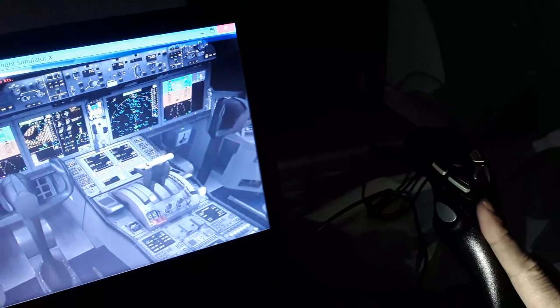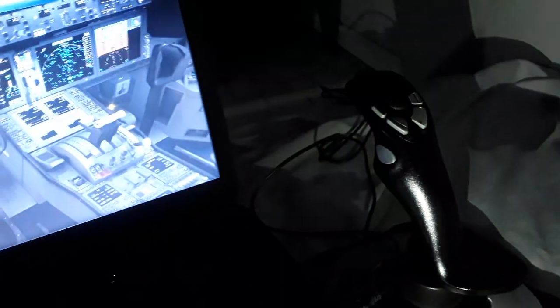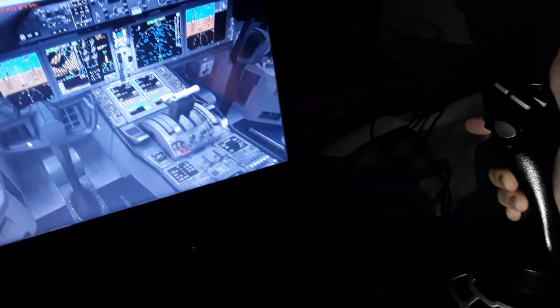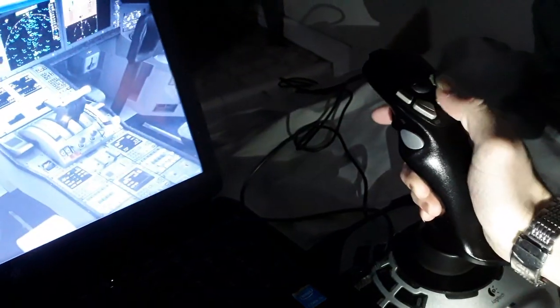Also the thrust levers over here. We can move forward or aft. We use this thrust control. I hope you like my side stick here. You will see a better view later. I control the thrust and the horizontal trim stabilizer. I can trim the horizontal tail of the aircraft as we fly.